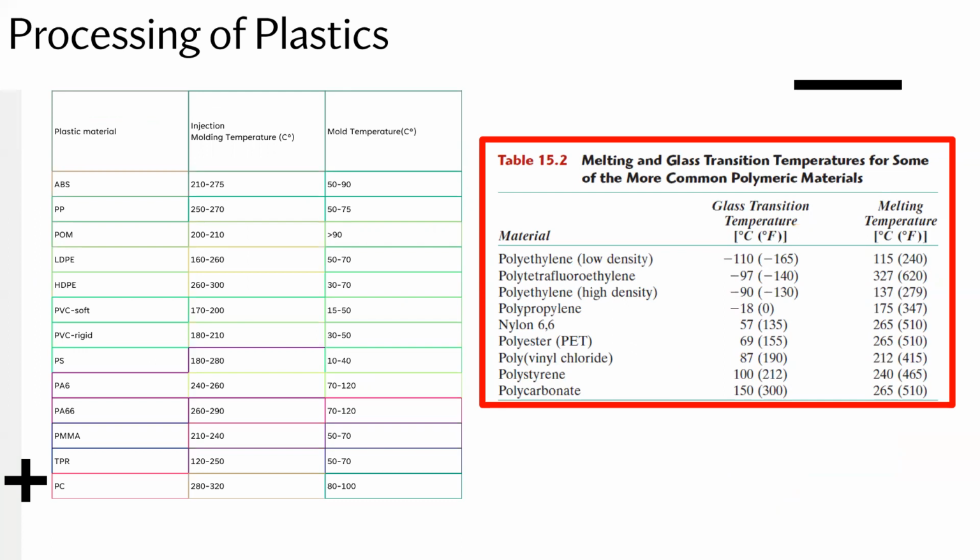So we discussed how these two are different. The glass transition represents a point at which the material crosses from a ductile material to a brittle material, meaning that it goes to a glass state, and it could snap easily and break and crack to a very sharp and flat surface. In the case where it's a ductile material above the glass transition temperature, if you stretch it or deform it, it's going to have a rather large elongation range until it actually breaks.